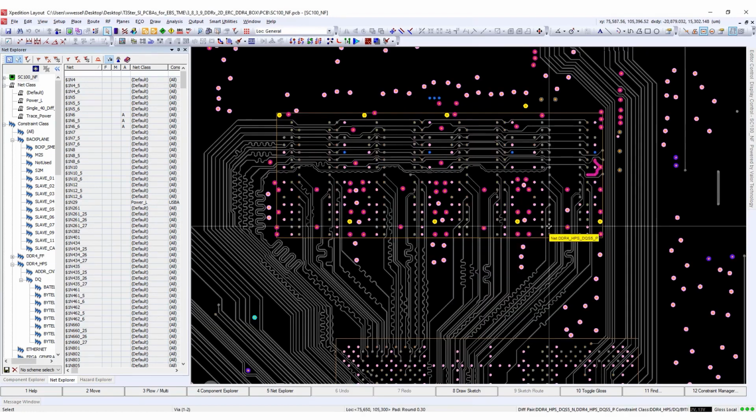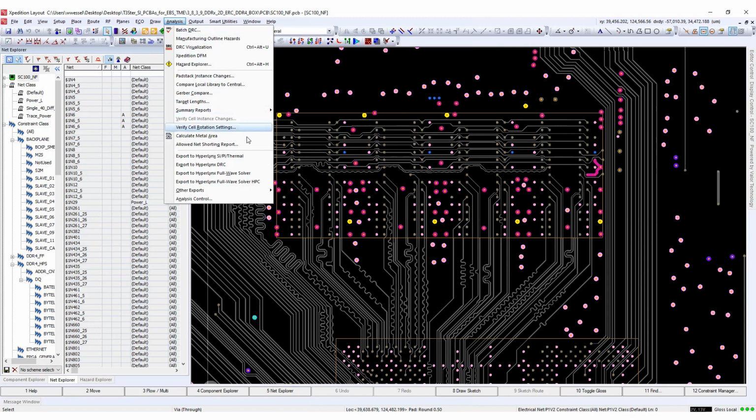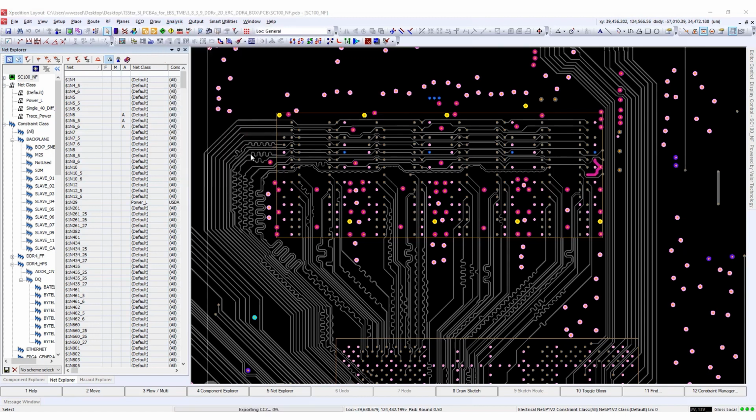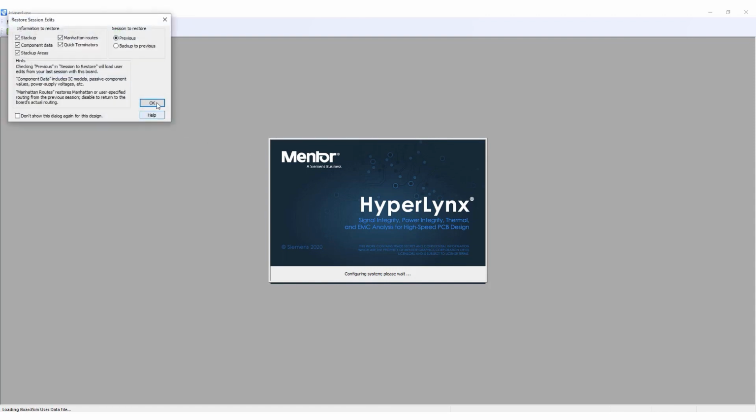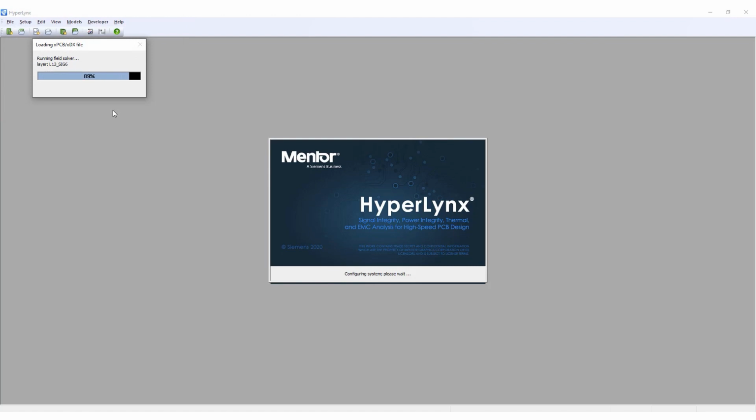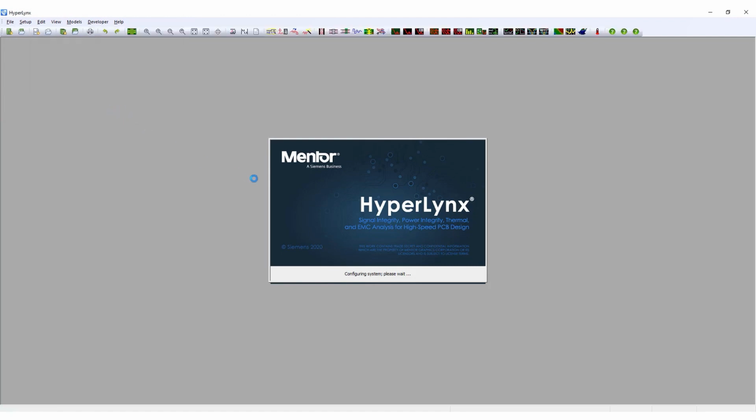After SEC constrained, routed and tuned the whole board, I want to ensure the routing quality of the DDR4 interface before the board is handed over to Rory, the SI/PI expert, for the final sign-off. This left-shift approach not only reduces the time for iterative cycles between me and Rory to fix issues. Additionally, I can learn and gain my own experience to avoid typical SI issues in the future.